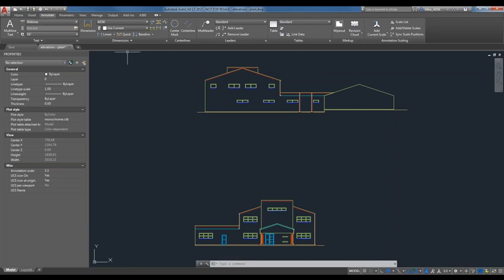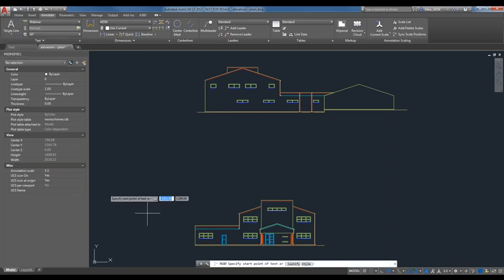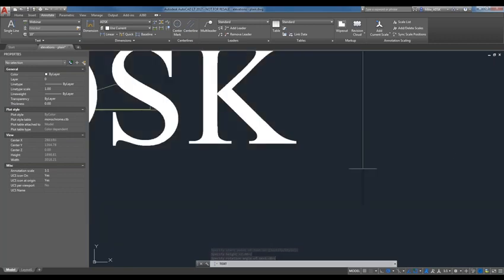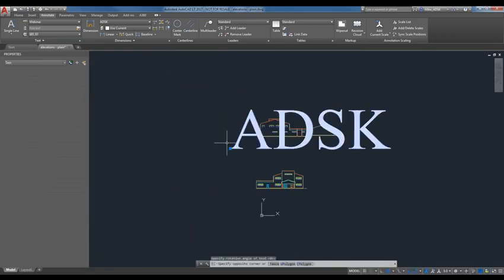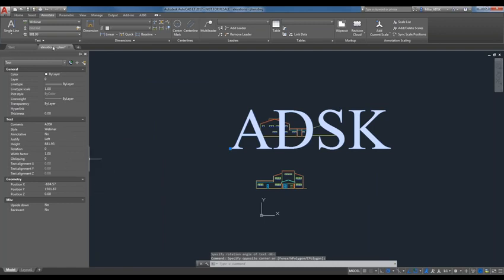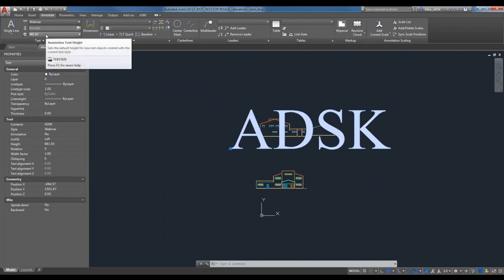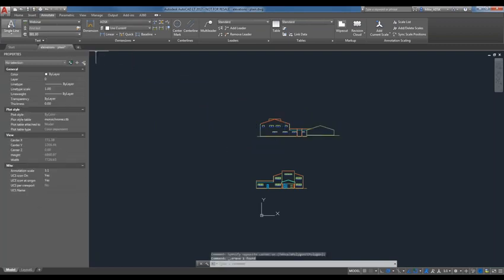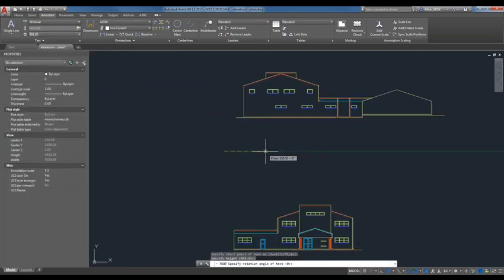So that is the text style that we're using right now. With your text styles all set, some of the basic things that you could do is make some text or MText. I'm going to start off with just a regular text line. That's going to be huge. It ended up being ridiculously big. The reason being that up here is where the text height shows up. Let me do that once more. See how that is 881? That's why it was so big.